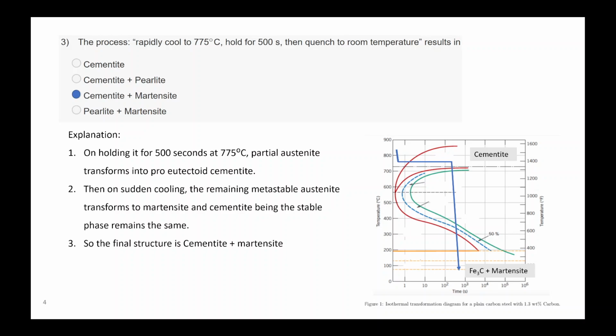Ma'am, in heat treatment, it will be actually changing the phase and grain boundaries, isn't it? So it should be affecting the elastic modulus. No, you can't change elastic modulus much using heat treatment. It mainly depends on the composition of your steel. It doesn't affect much if you are changing your heat treatment. Elastic modulus is not very sensitive to heat treatment.